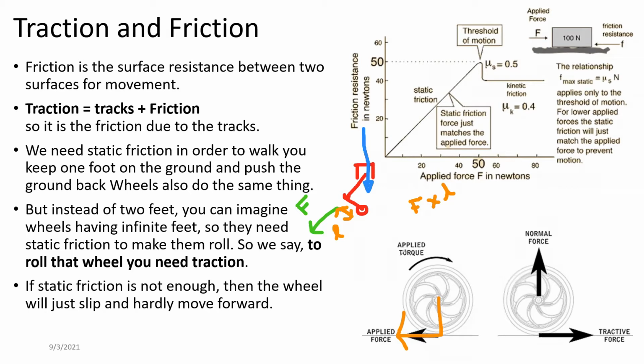So this applied torque, this is the torque. That torque is delivered from this equation here, F into L. That force then goes to the gearbox, the transmission, the drive shaft, and everything, and comes back to the wheel. And when the wheel is rotating, this F is applied here not as capital F but as a simple f, because it has to go through a lot of components.